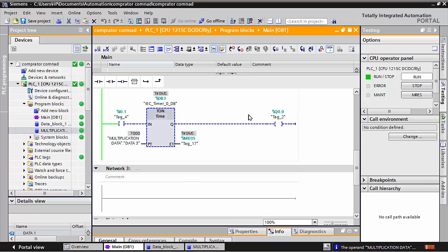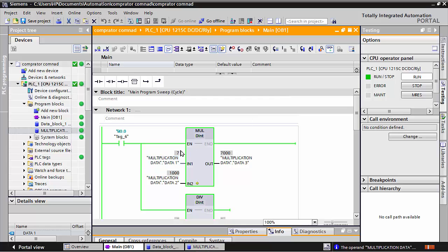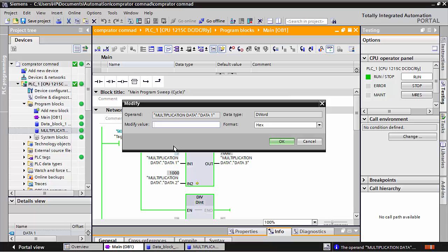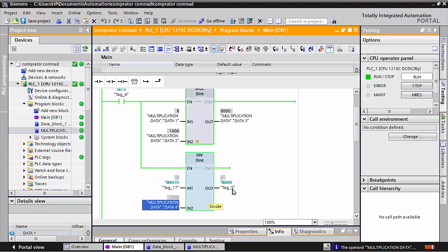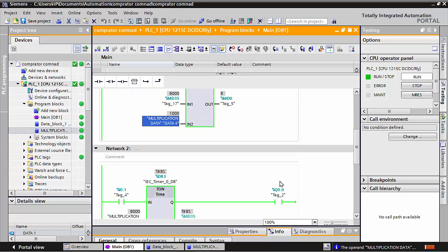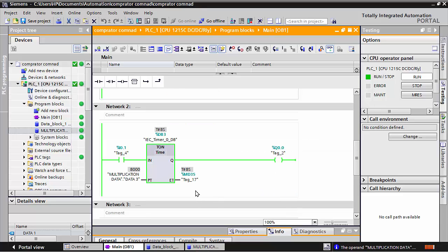And if I like to change this time also, I don't need to go anywhere, and here I only change it, put 8, and then you will get 8 seconds, yani make it execution on, and you can see here also that running time 4, 5, 6, 7, 8 and 8 seconds after your output will be on. That is simple.